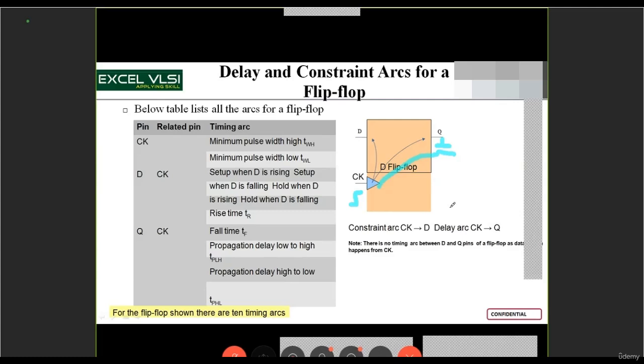Under the sequential cells, you can check it once again. You will have a cell delay table, a rise transition and fall transition table, and a setup table and a hold table. With respect to the clock and D pins, there is a table given for each and every sequential cell, where the setup timing and hold timing of that particular flop will vary according to the usage proposed in the gate level netlist.